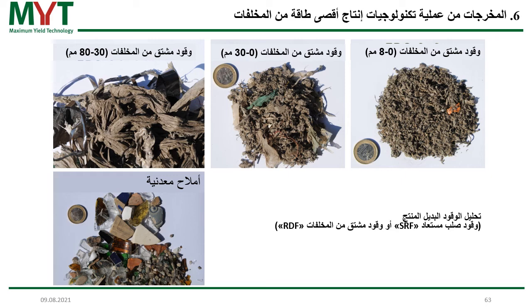We normally name it in Germany RDF, refuse-derived fuel. But when you work with the cement industry, you will come across the name SRF, solid recovered fuel. SRF normally refers to a process, and the RDF has to undergo a process to be named SRF, because you have to maintain a high quality, you have to be low in pollutants, and the chlorine content has to be low, otherwise the cement industry cannot make use of your RDF, especially when it comes to chlorine.